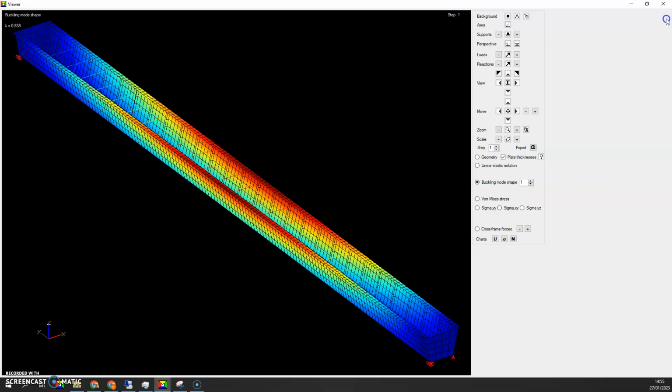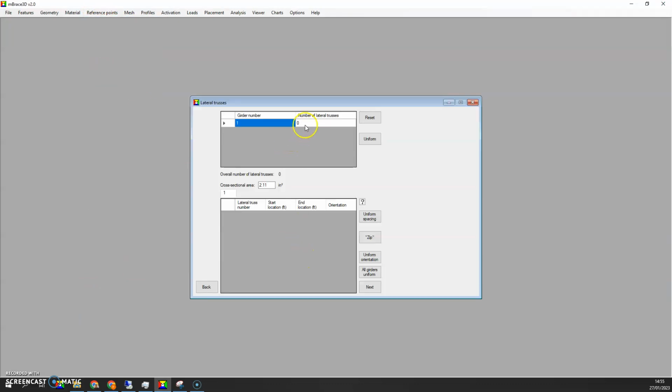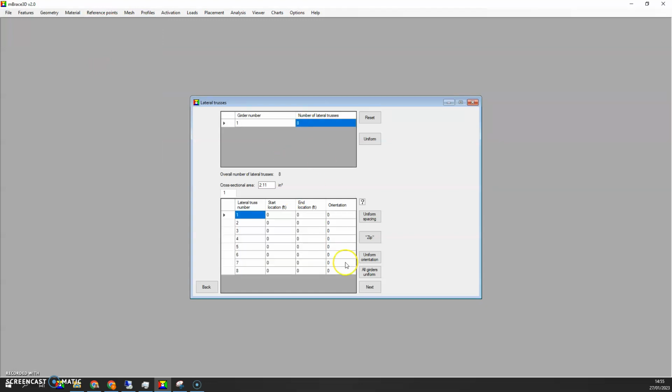One way to do this, as researchers from the University of Texas and other places have shown, is that just by adding a few top lateral braces, you can really engage the torsional stiffness of the tub. So let's enter some top lateral braces here. Let's do 6.32, 6.32. Here it will be up to 12.64, 12.64.